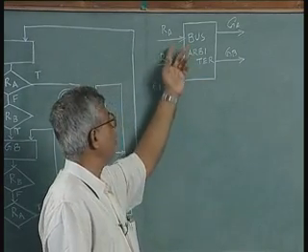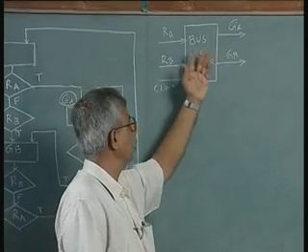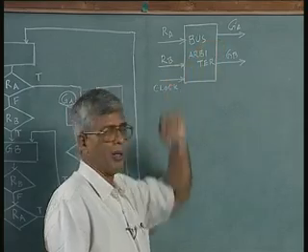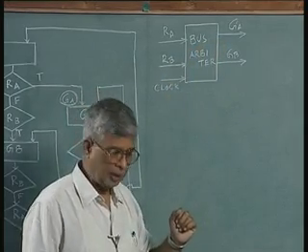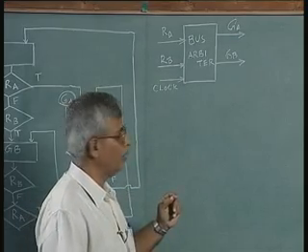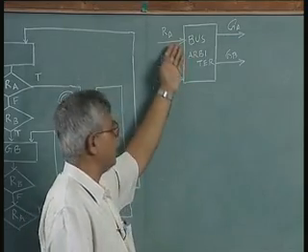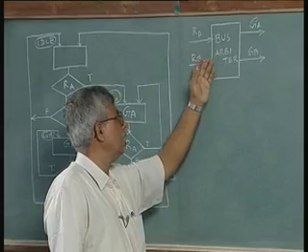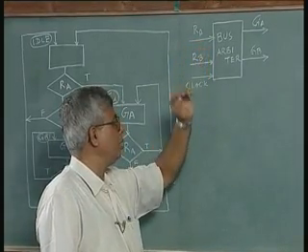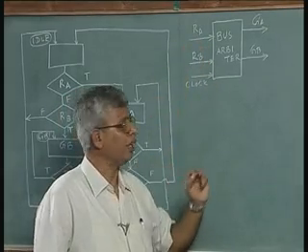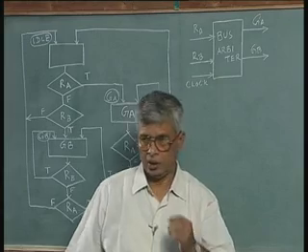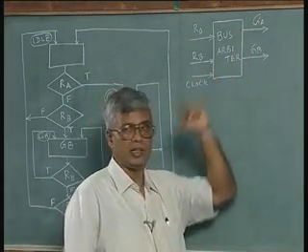You see, normally only one of these requests comes, it is either the unit which requires or requests the bus gets the bus. The problem or contention comes only when both the units require the bus at the same time. So, we have prioritized GA as higher priority than GB, unit A having higher priority than unit B. That means if both RA and RB come at the same time, RA gets preference, that means the bus is given to unit A or GA is generated.